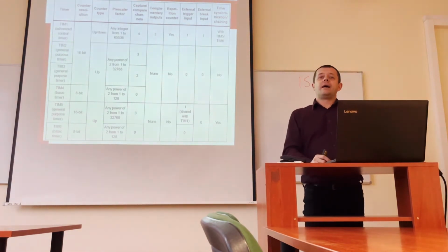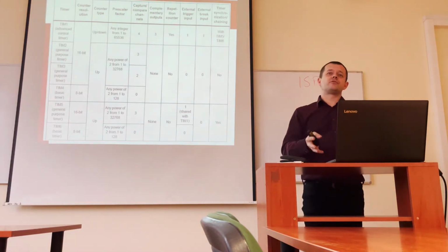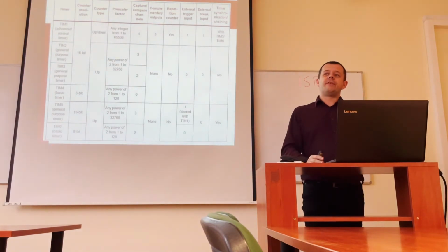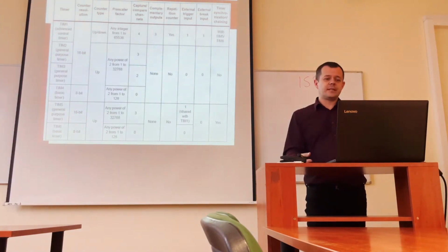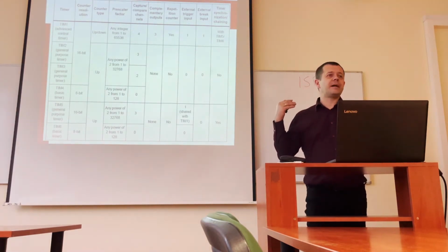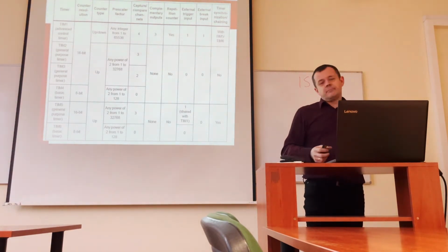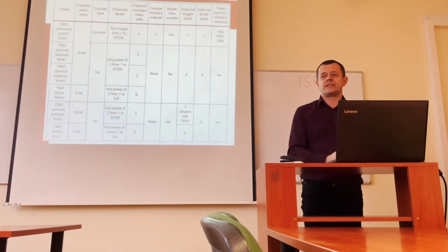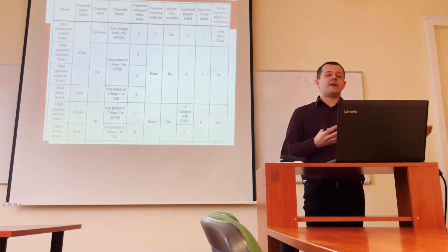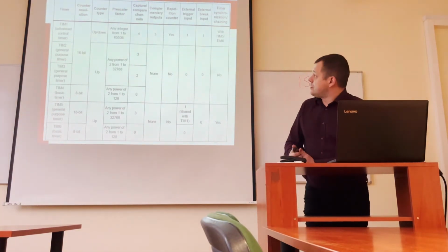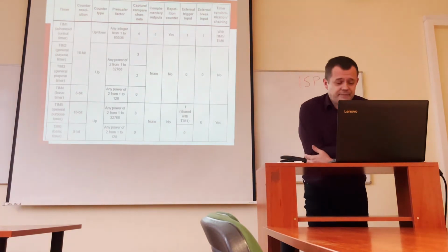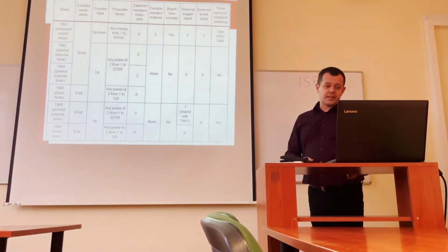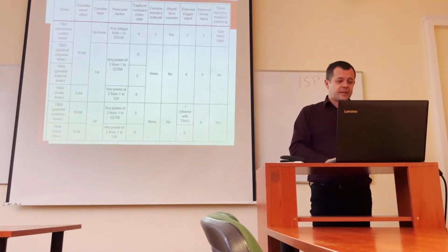In the case of microcontrollers, because we've got many timers available, usually we can find in the documentation this kind of table, because the functionality of the microcontroller timers differs. Usually in microcontrollers the timers are not symmetric, so we have various timers with various functionalities available. Here is an example from STM8, just 6 timers for one of the STM8 models, but the list can go on really long. As I mentioned, today microcontrollers tend to have about 20 timers with varying functionality. So it's not possible for us to analyze every possibility that exists on the market. Let's analyze this table in the case of STM8.